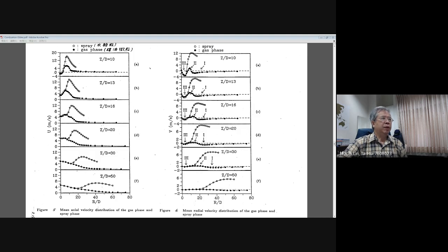The simplex nozzle has a swirling motion. The influence from the circulation force will open your spray angle, and you may not have too much water droplet in the center region. Actually, they produce a so-called hollow cone spray.